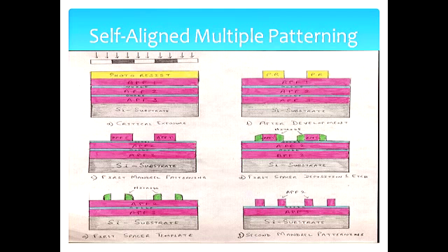All these etchings, especially for the mandrel and the spacer, take place with reactive ion etching, because I need very anisotropic and very straight edges. Oxide layer etching is a wet etch process. Since it's a very thin oxide layer, a quick HF rinse is just done to get rid of it.